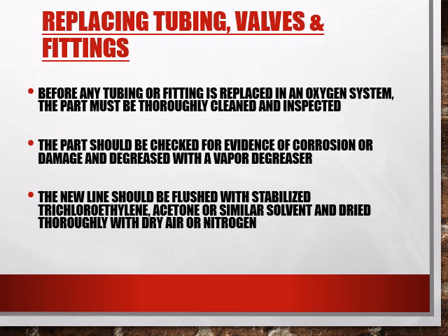Before replacing any oxygen system component, it must be inspected, cleaned, and thoroughly degreased. Approved solvents like acetone or stabilized trichloroethylene are used for flushing, followed by dry air or nitrogen.